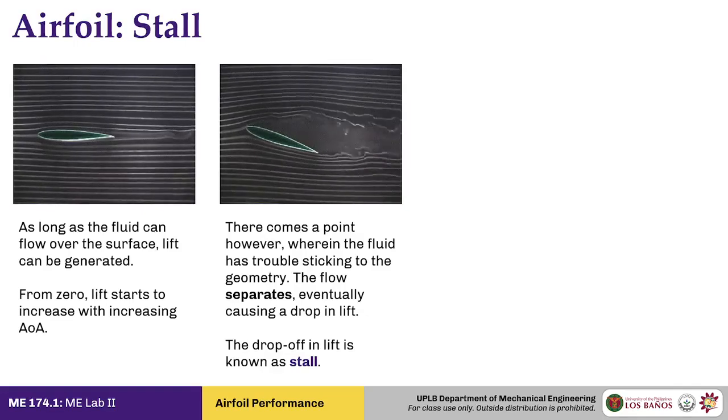So stall is a very dangerous situation for fixed wing aircraft because the moment you hit stall, there is essentially no lift generated. Or at least there is not enough lift to counteract the force of gravity. You will have a very dangerous situation depending on how high you are above the ground.